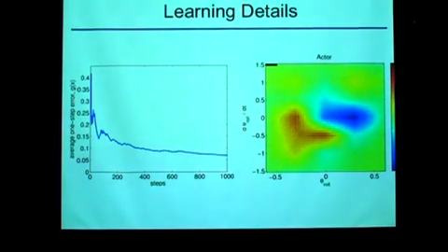It was very important to be able to add noise by making a persistent change in my policy. So adding noise meant this whole function would change a little bit, and then it would stay constant for that whole run, and then change a little bit. If you add noise every dt, you have to worry about it filtering out with motors and stuff like this. This was a very convenient discretization in time on the Poincare map. I think that was one of the keys to success.